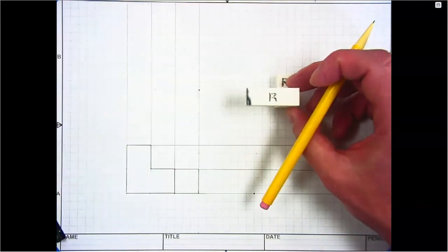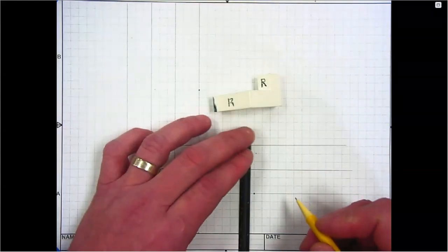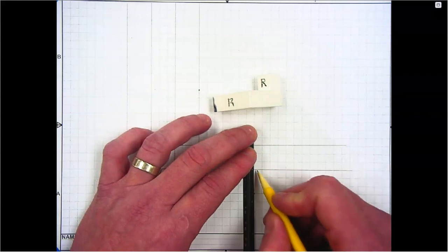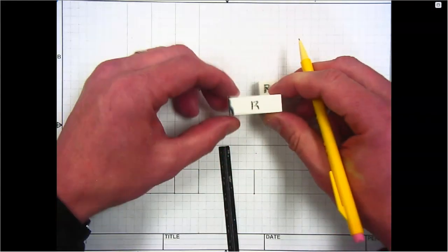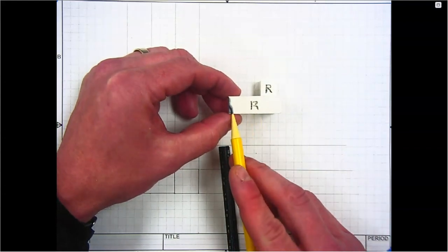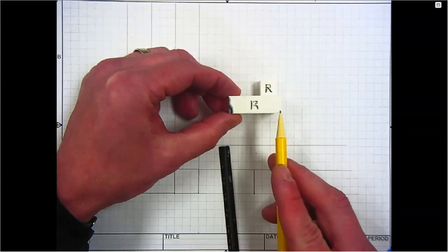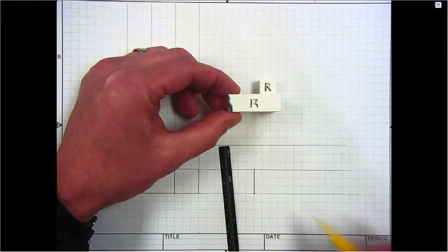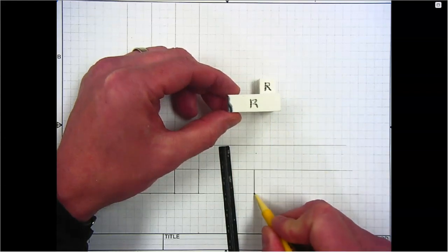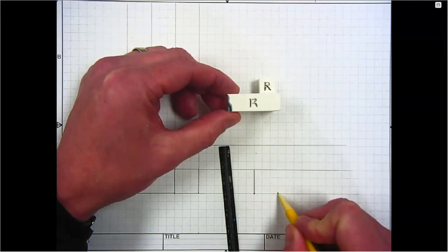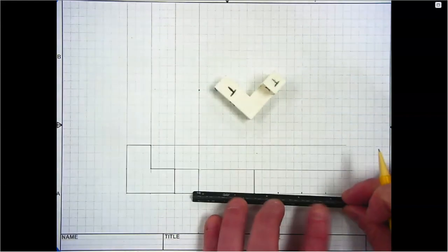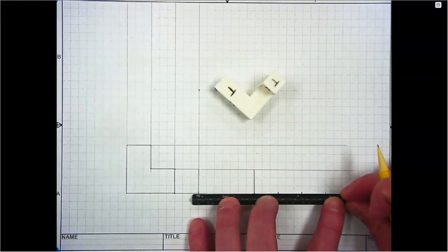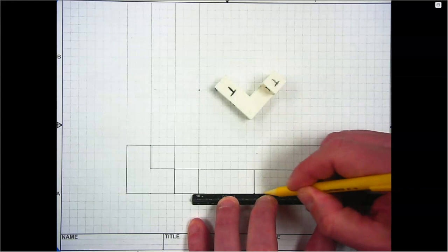And so that goes up one block or 3 cubes, and I'll create the line. From there, it goes over in the depth dimension 3 cubes, so I'll go over 9 spaces. And I'll put the base in, and this is going to describe the overall depth of the part.